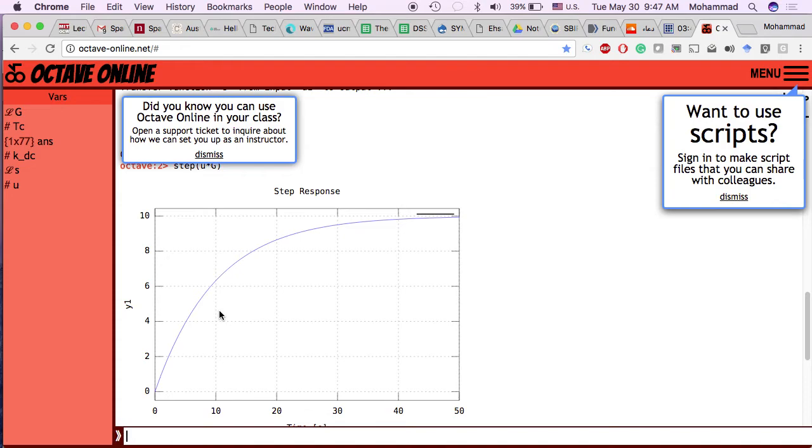You can immediately look here and tell me the DC gain must be 5. So you have the numerator of the transfer function. You can look at this and calculate the time constant. So you have tau. So you have the transfer function. Can you see that? So by having only the response of the system, you can back calculate. You can go back and find the model of the system.